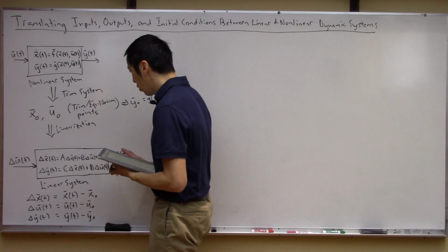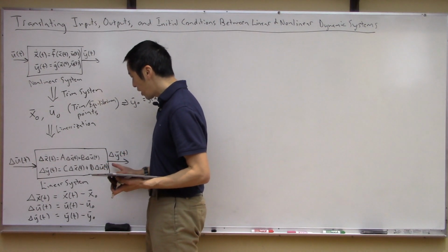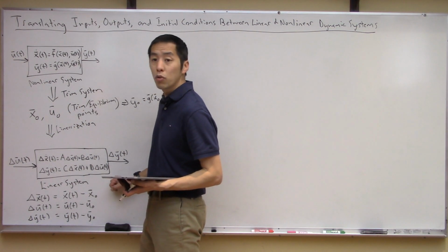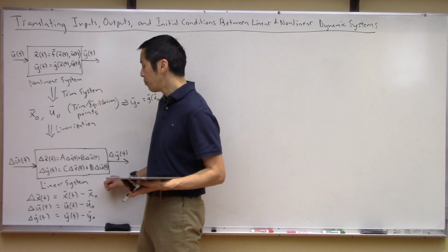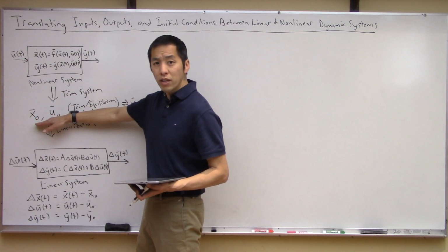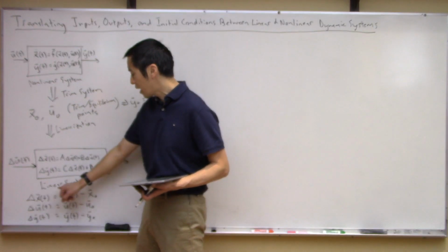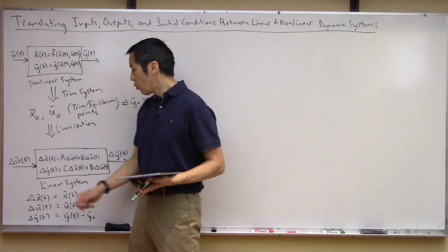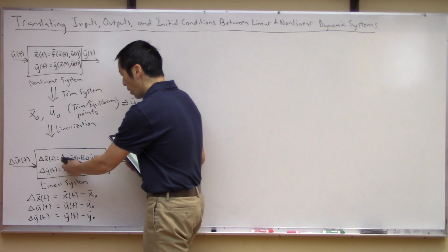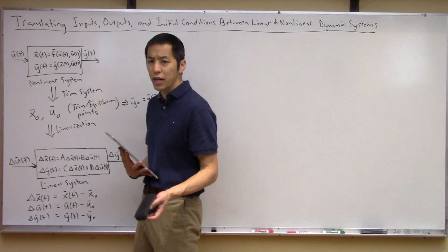Okay, so now I think we've got all the signals defined. The thing I'm being explicit about is the notation. When you do linear analysis down here, you're really trying to understand, or simulate, or analyze how the overall system operates near this point. This is describing perturbations from the trim point. That's what that capital delta is. What makes this confusing is that in a lot of literature, people get lazy and drop the capital delta notation because they don't want to be writing it all the time.